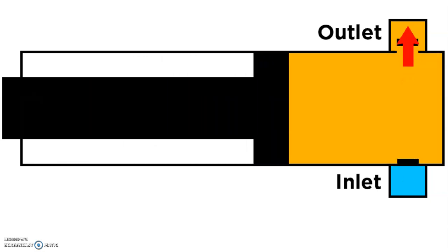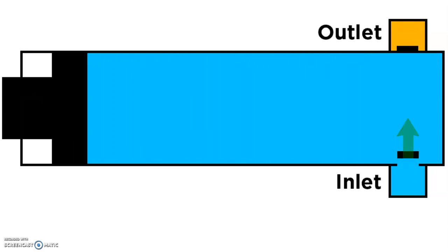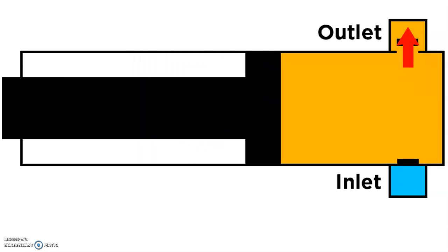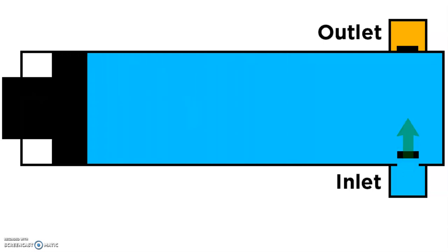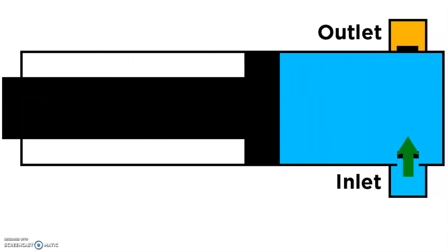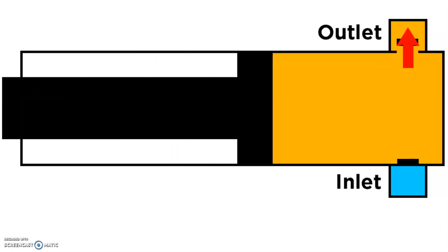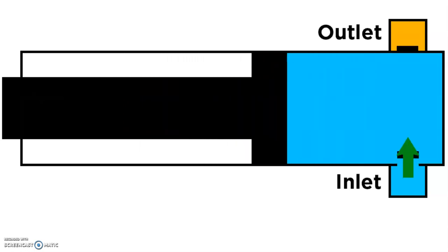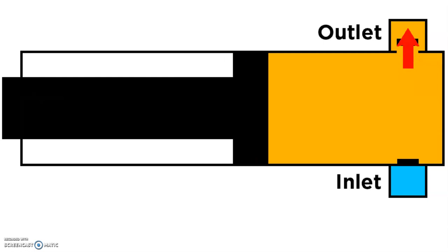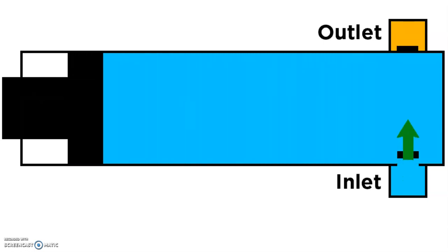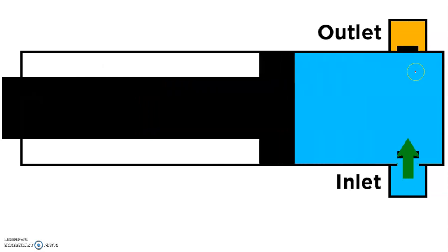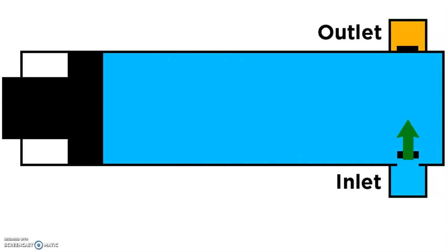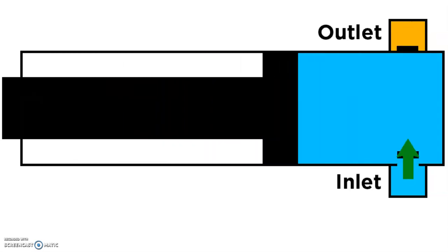Usually these mud pumps are reciprocating positive displacement type of pistons, and there are two types of them: the 2-cylinder or duplex, and the 3-cylinder, which is called triplex pumps. The duplex pumps generally are double acting pumps. When we talk about double acting, it means that the pump both has suction and an output, in both the forward and backward movement of the piston rod.